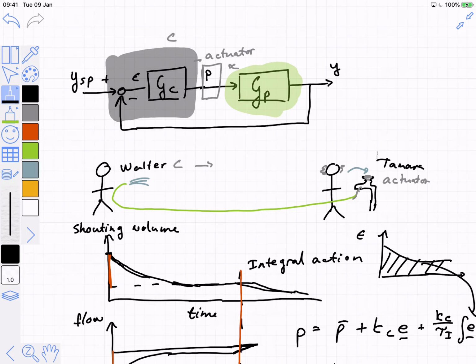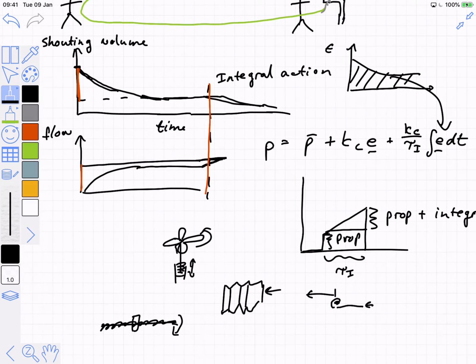Now the controller version of this is that if you had some kind of a mechanical system like this, it could be that you've extended your bellows further than the manipulated variable mapping can actually go open. So you keep turning, you open it even more, nothing happens after a certain point.